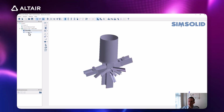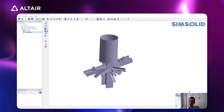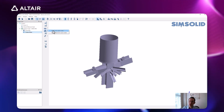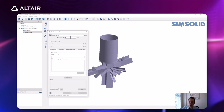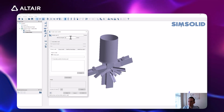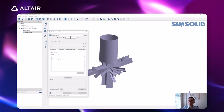So I'm going to click on this connections workbench, and through here, I have all these different tools to define different types of connections. And I'm going to use the seam welds option. I can click on this and say create new seam welds. And I can choose a section size. I'm going to say I have a 5mm section size, and the minimum length I'll set to 40mm. The reason I'm setting a minimum length is that there may be certain edges, like maybe the small edge of my flange, that I don't want to worry about welding, as you'll see later on.